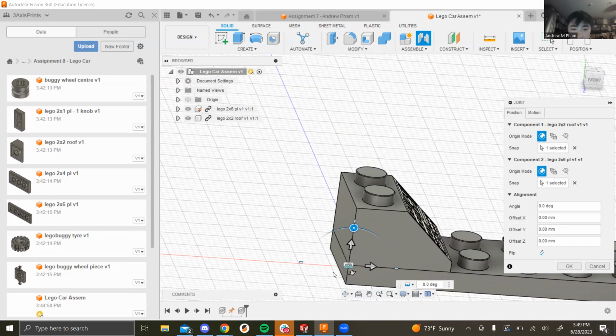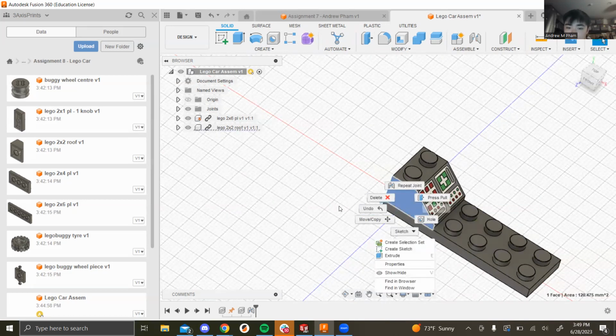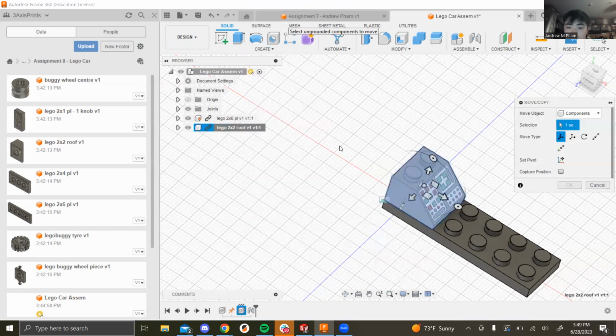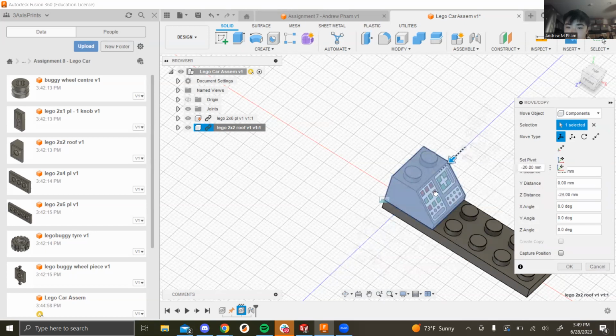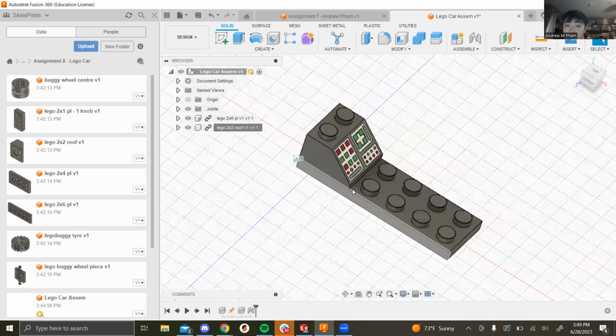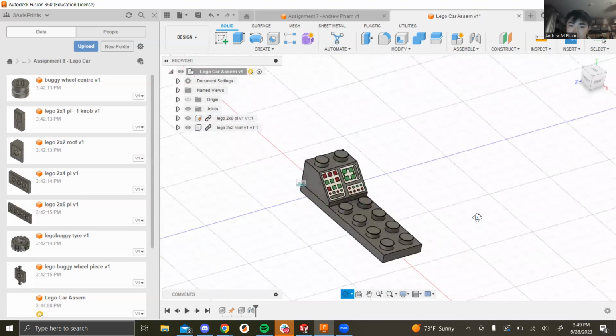So that just lets you know I want this to be rigid. And we just selected these two corners. And then you just select OK. And now these two pieces are connected, right? So if I try to move this, it just won't let me anymore. Because if I drag it, the thing will drag, but the part won't move. And that's because it's joined with the base plate. And it's also why it's important that you ground your first piece so you don't just start dragging your model all over your workspace.